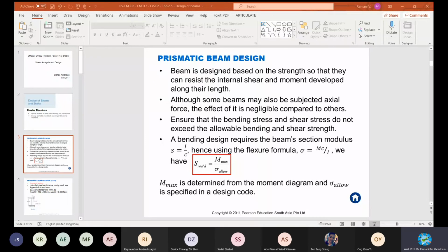fillet, I think. Fillet and the bolt. They use a fillet to connect both, and on top of the fillet they put the bolts. Bolts are connected. See, these two bolts are supporting the flange and the web, and this one supporting the flange and this web. Like this, the section may be either welded or bolted.